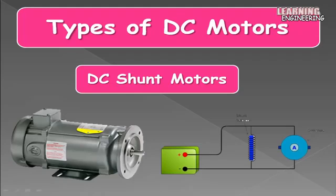DC shunt motor. A shunt DC motor connects the armature and field windings in parallel, or shunt, with a common DC power source. This type of motor has good speed regulation even as the load varies, but does not have the starting torque of a series DC motor.